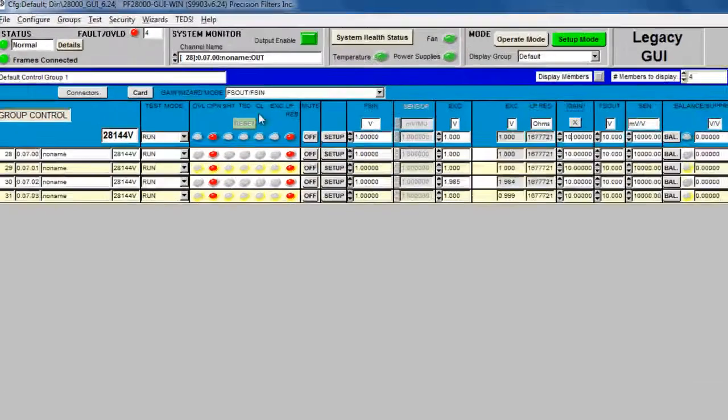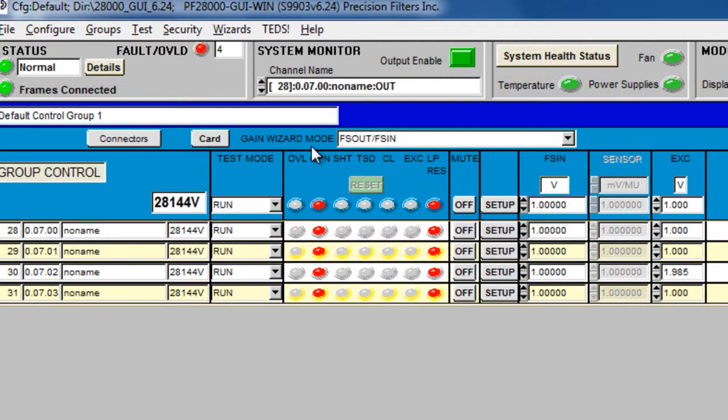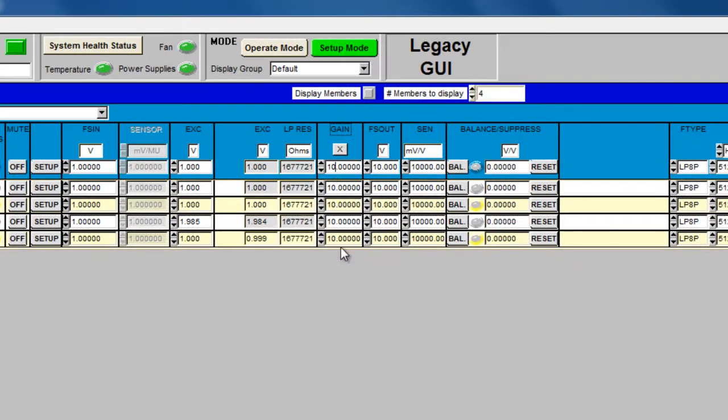in the software to achieve the output sensitivity that is desired for the measurement. To achieve the desired voltage sensitivity at the amplifier output relative to the input stimulus, the amount of amplifier gain must be scaled correctly. An example of the scaling of the amplifier gain would be for a strain gauge circuit. To provide the desired correlation between strain seen at the strain gauge and the output sensitivity in millivolts or volts per microstrain, sensitivity in the amplifier is dictated by the channel gain.